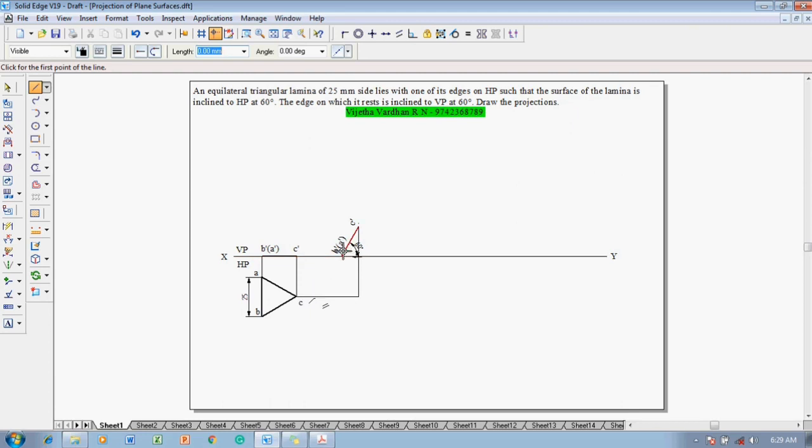In the same fashion, the next right extreme corner will be B dash, A dash. Select that B dash. Now B dash projector is going to be up to here. Join B dash to B, and similarly along with B we have A. Let us connect back the A.